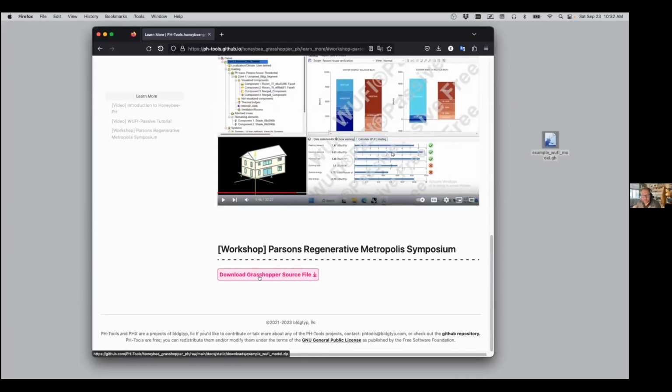I see in the chat there, Justin agrees. It's always better to create a separate 3D model for Passivhaus output. Yeah, that's certainly been our experience. Justin says you need Rhino 7 to make it work. That's correct. This will only work on Rhino 7 or above. We are not 100% sure if it works on Rhino 8 just yet. We're still testing, and we're updating that right now. Obviously, Rhino 8 is only in beta release, but we'll test everything and upgrade it for Rhino 8 at some point. But you're right, Justin. We need Rhino 7 for this to work right now.